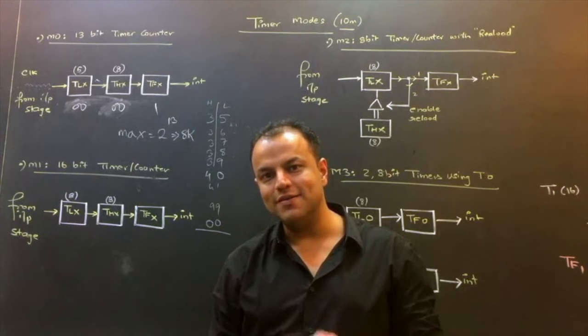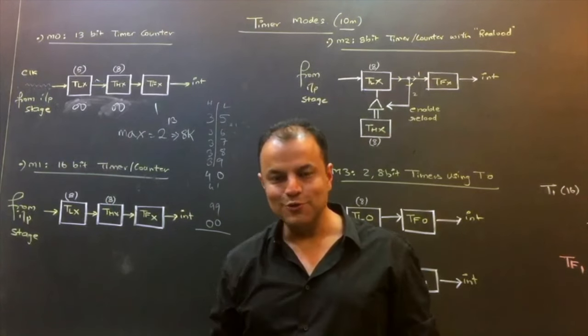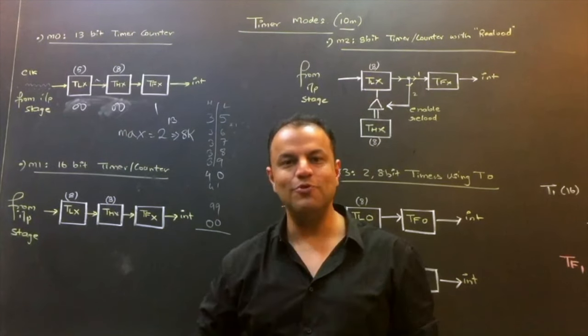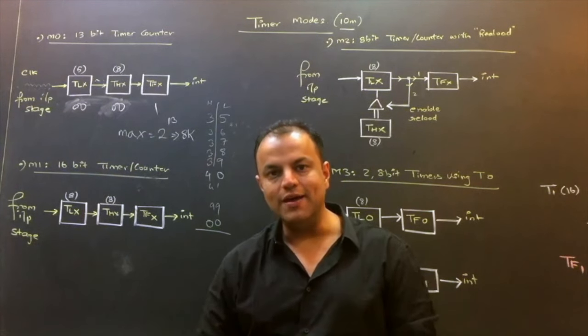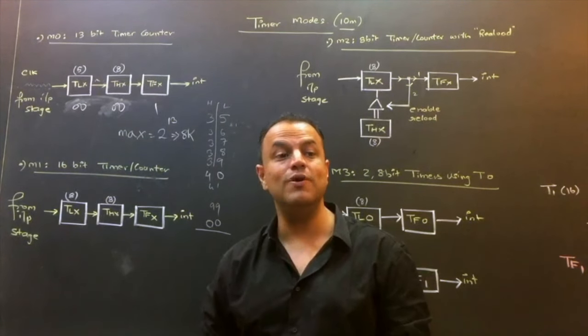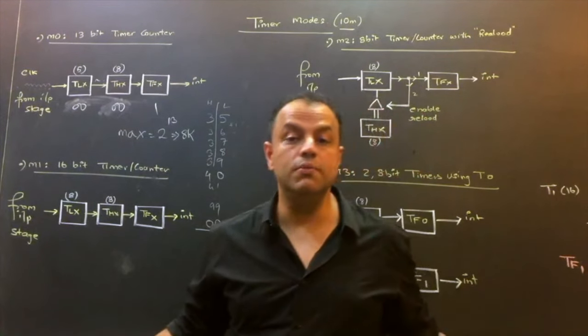That means, can you see there is a division by 32? And this is a mode to divide a frequency by 32. You think it's a coincidence? No. This mode is used to create an artificial serial port where you can divide a frequency by 32 and get the same baud rate which the actual serial port does. Only because you wanted to know.